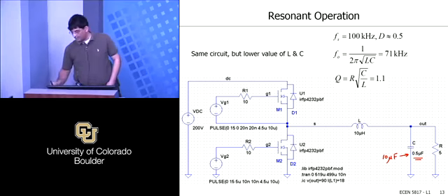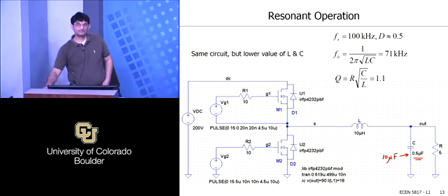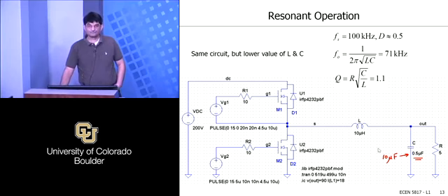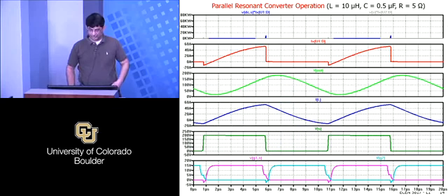Okay, what do we expect now? You have a lot higher voltage ripple. Yeah, you're going to have a lot higher voltage ripple, and because the voltage is no longer going to be constant on this side, the current in the inductor may no longer look triangular, right? Because the triangular basically assumed you had constant voltage across the inductor, and so you had a straight ramp up and ramp down. Okay, let's simulate this and see.